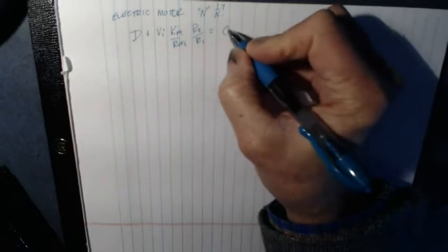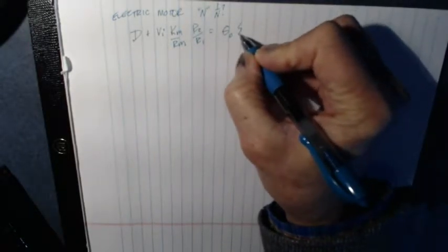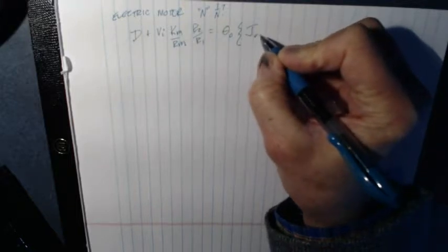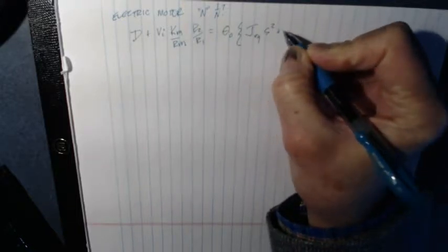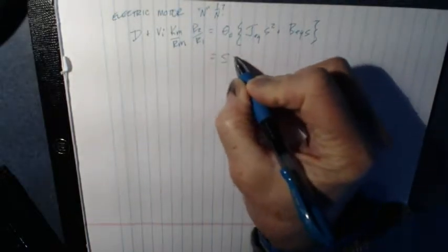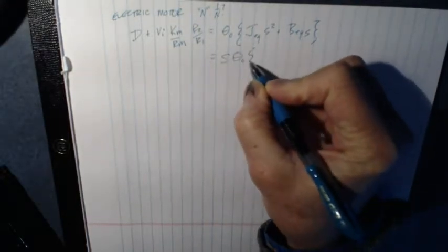And so then what we've got is theta out, and we've got J equivalent S squared plus B equivalent S. Now, that's perfectly good if we're looking at wanting to know how the motor position changes with time. What I'm going to do now is take 1 step backwards and make this S theta 0.